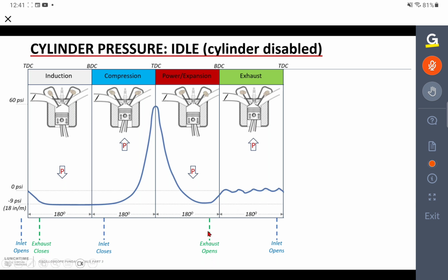So as the exhaust valve opens, atmospheric pressure is effectively pouring into the cylinder that was at a low pressure or a vacuum, and it will now rise up to about atmospheric pressure, especially once the piston starts to rise and force the air out of the cylinder on the exhaust stroke. So again, don't forget, we haven't created any combustion, so we're just at normal negative pressure here.